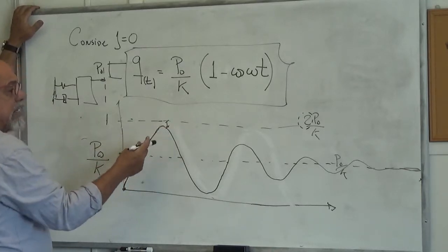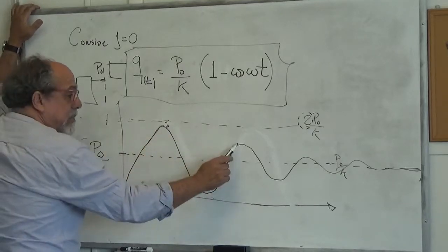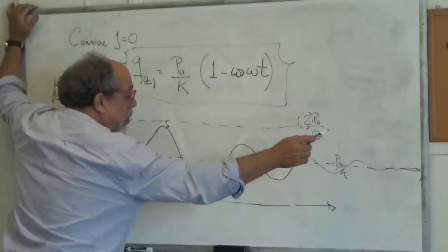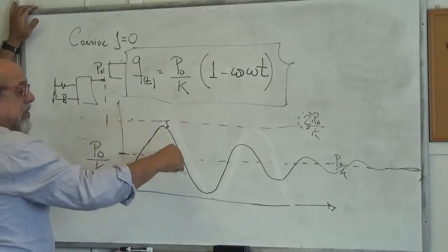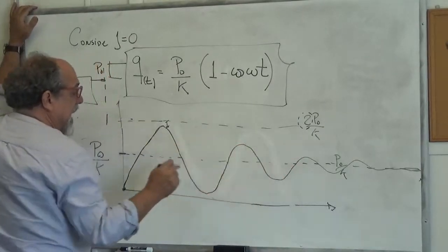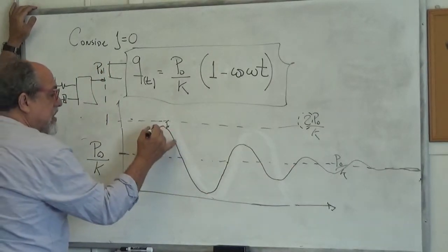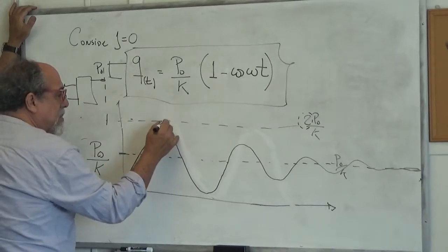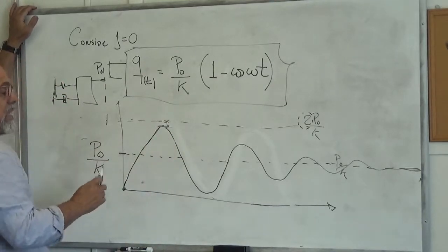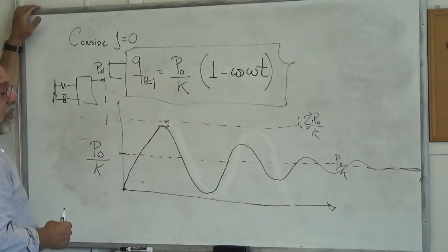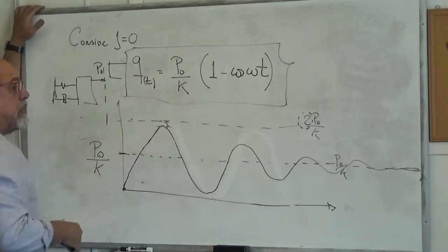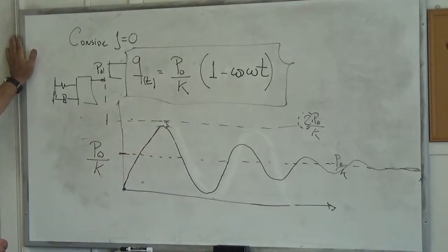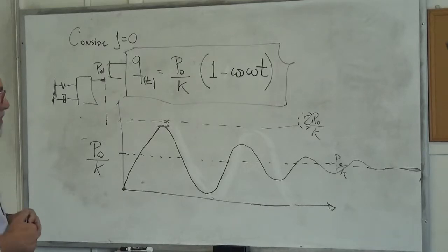For the second and third peaks, the peak response is obviously decaying. But if your system design is governed by the maximum response, then the maximum response would occur on the first cycle, and is going to be pretty close to 2 for reasonable values of the damping.